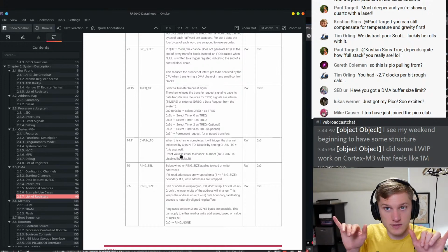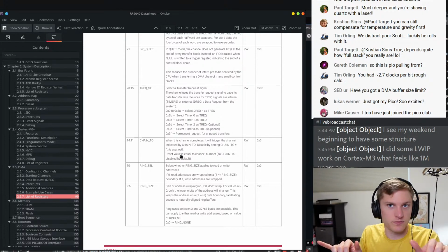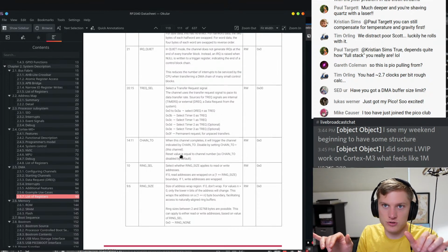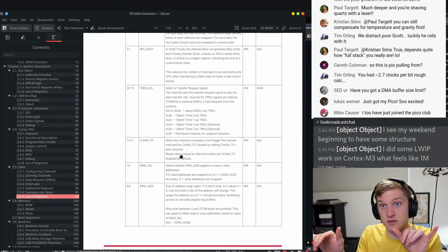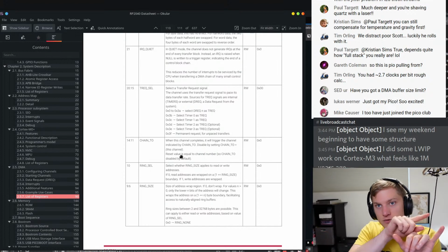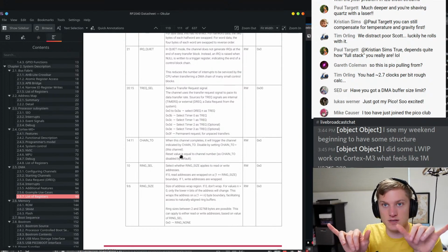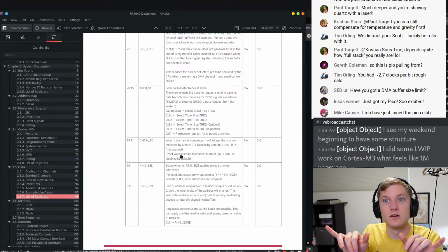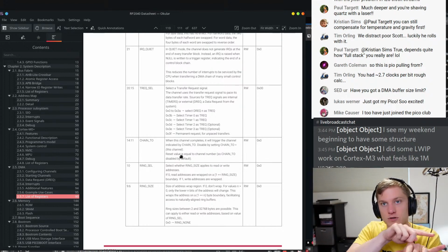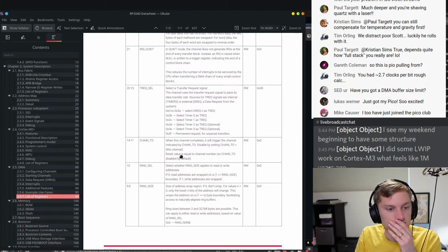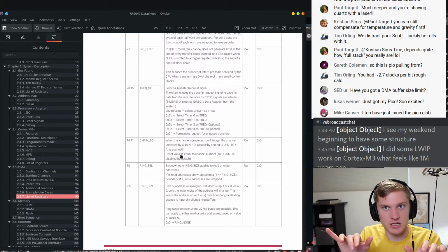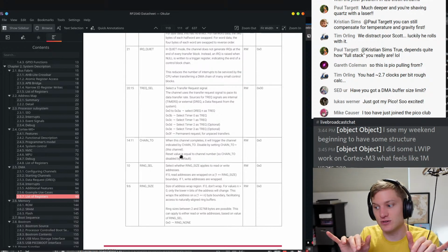So we'll have 2 DMA channels, one for buffer A and one for buffer B. And then with chain 2, you chain this DMA's channel to the other one, so that when you finish this transaction, it automatically keeps going. And that's the moment that you have something that says, oh, I've got to fill this one up now, before it gets to the end of this buffer and returns back. So that's one thing chain 2 can do.